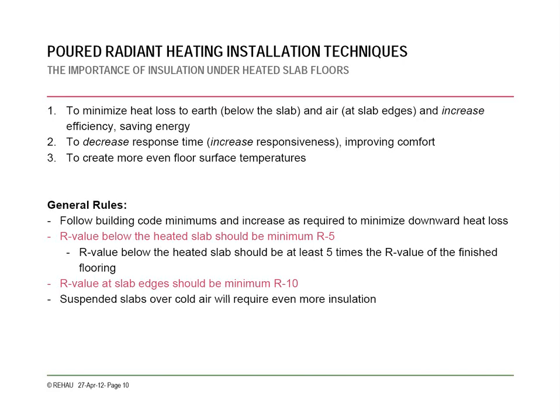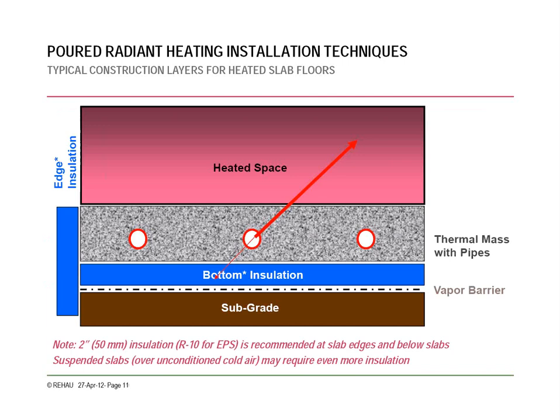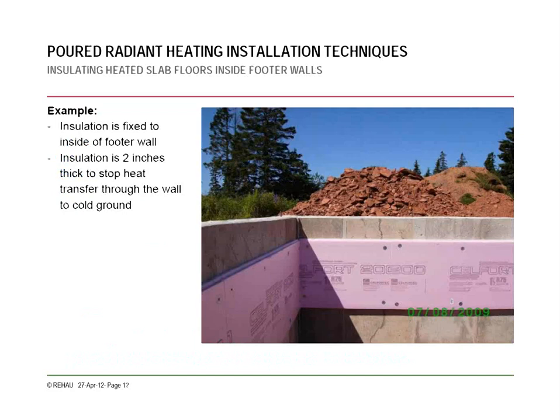If you're doing a joist-based installation, as I'll touch on in a little bit, you definitely want an increased insulation value to make sure you're driving the heat upwards. Here's another look at the same thing. Make sure you're using edge insulation and bottom insulation, especially when you're working on grade. Here's another example of how you want to do your edge insulation.